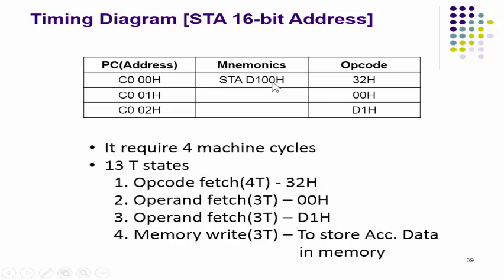Next instruction, that is memory device related instruction. Store instruction, that is STA 16-bit address. For example, suppose STA D100. So size of the instruction is 3 byte. Okay, so in the opcode field you will find the opcode for this STA, its opcode is 32 hex.